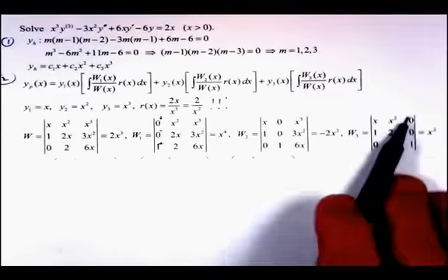Yes, if it's equal to 0, but points of inflection are where what changes? Concavity, that's it. Okay, so point of inflection, concavity. So basically what this is telling me is that the bending moment graphically has to do with concavity. You know, something's concave up or something's concave down. We have this idea concave up is a cup, concave down is the other way around.